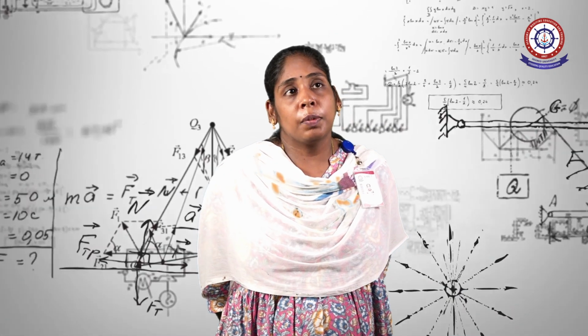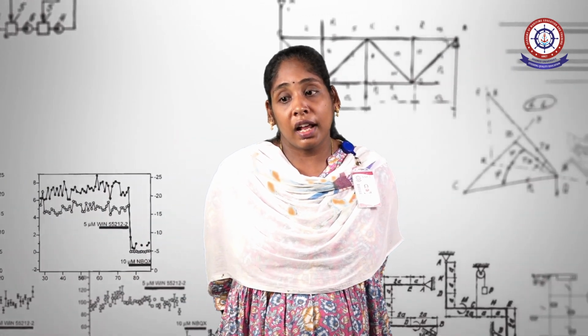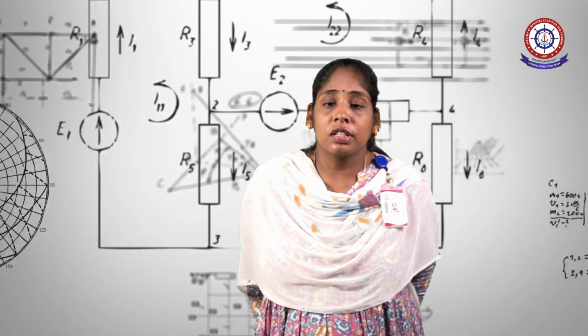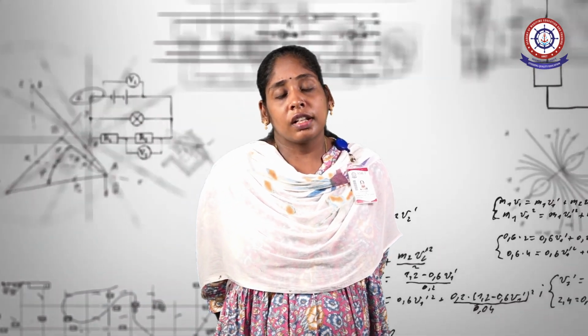So the frequency plays a major role here for electric propulsion. A common electric propulsion package fitted on many cruise ships consists of a 21 MW gas turbine driving a 21 MW generator that powers a synchro converter and cyclo converter.